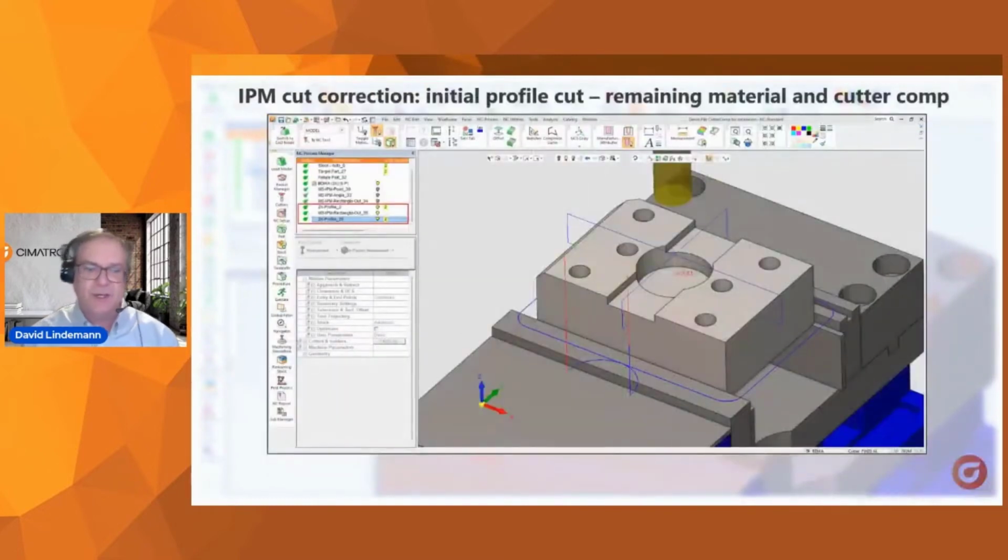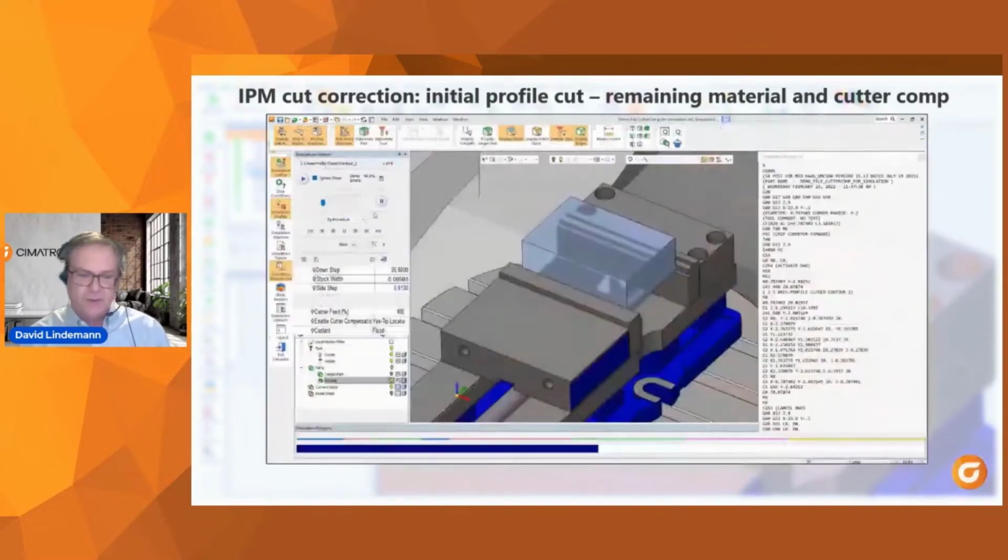Let's go back to our example here. We've got the pickup done, the setup. Now we're going to take a profile cut. We're going to use the probe to get the measurements, and then we'll cut it again. Okay, so here you see it stepping through, getting the profile cut that we need. It'll go around, and then we'll be able to take our measurement. So if we advance forward here,